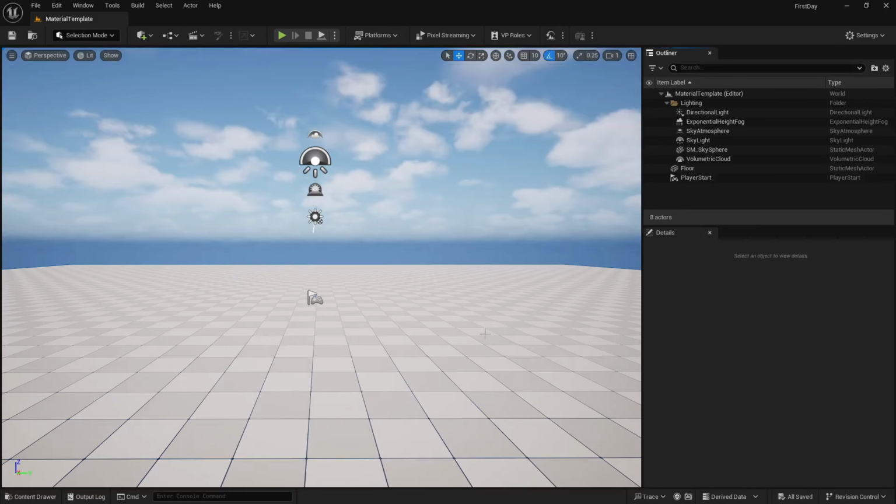If you have used a 3D application like Blender, Maya, or 3ds Max, you know that they provide a default material. Let's say you are using Max and Corona, then you have the Corona physical material. If you are using Maya and Arnold, then you have the Arnold shader. And if you are using Blender Cycles, then you have the Principled BSDF shader. So they are already loaded, but in Unreal Engine, you need to create that master material once, so you get all the parameters like the roughness slider, normal intensity slider, and all that stuff, and then you can just create some material instances and change them according to your needs.